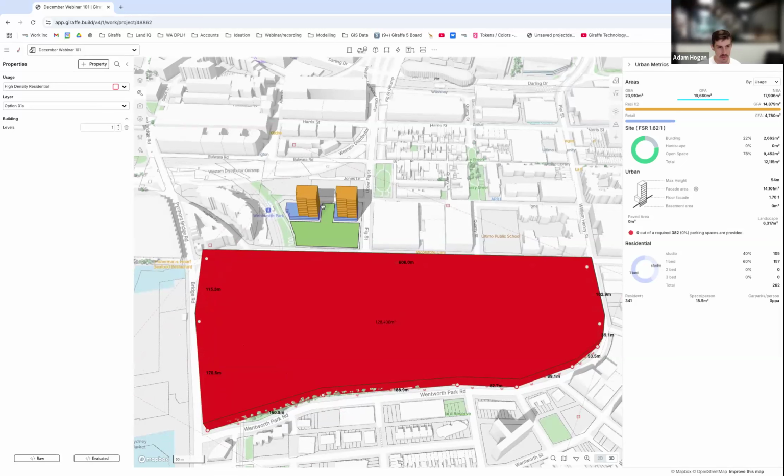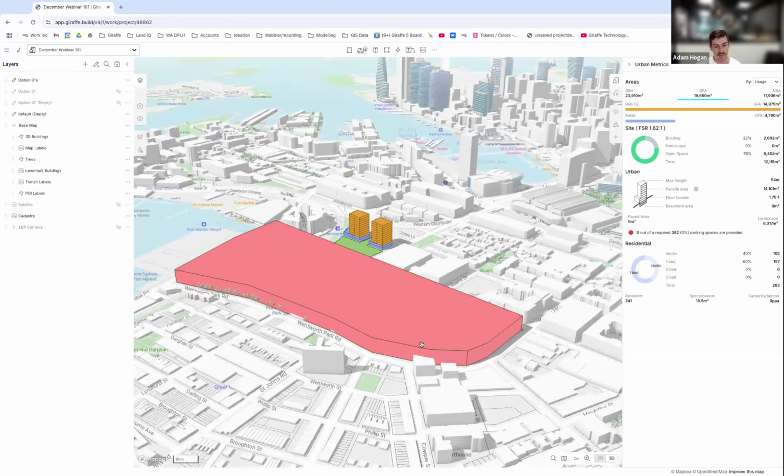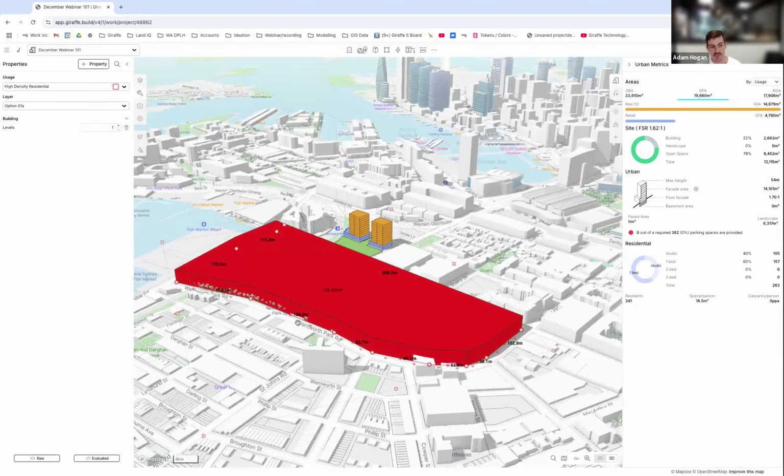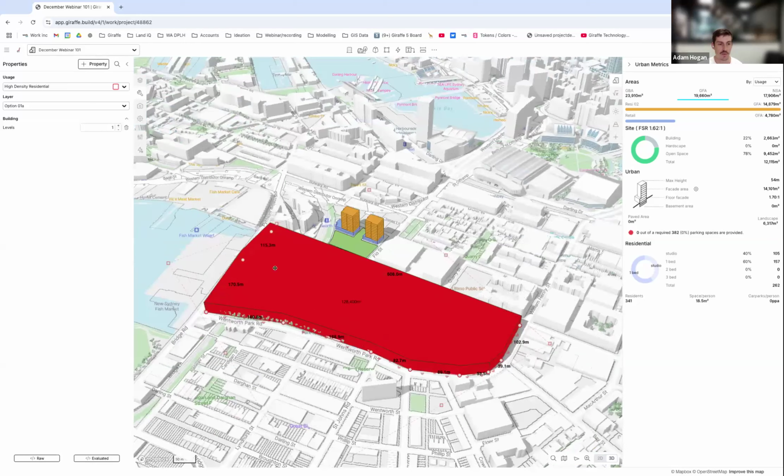And that's when we would start to use the building sections, which I've done there. But this would be at that larger scale. And we can still build in some assumptions into this in terms of the site efficiency and an FSR. So we could say 80% of this site is actually going to be subdivided. The remaining 20% is allowed for infrastructure, roads, and whatnot in the subdivision. And then we can apply FSR to that remaining 80% to get an indication of what yield we could get out of that at a very high level, I must admit, but still getting those metrics from that envelope scale.